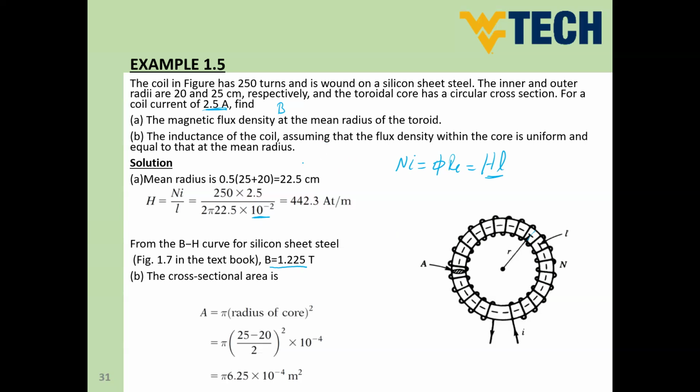Otherwise, if you need a detailed model, it's going to be a very complex model, and most probably we may end up using finite element methods or a finite element program like COMSOL, Maxwell, JMAG, all of these types of programs used for multiphysics and finite element calculations. However, for the undergrad level, we all of the time assume that the flux is uniformly distributed within our magnetic core. So now we need to get the inductance.